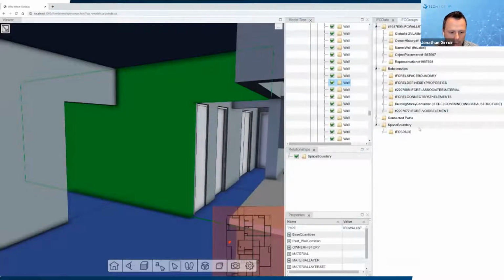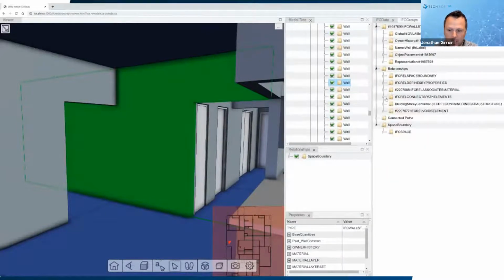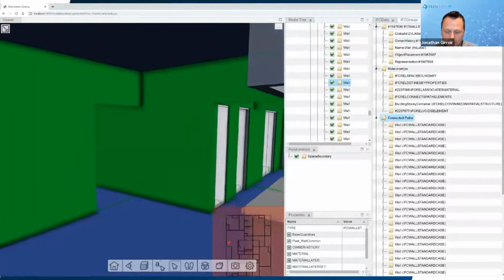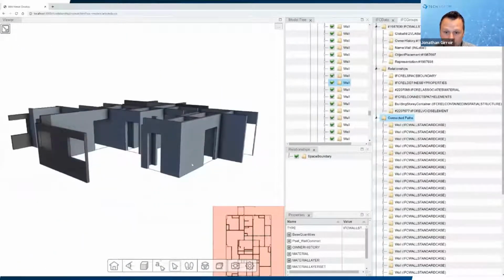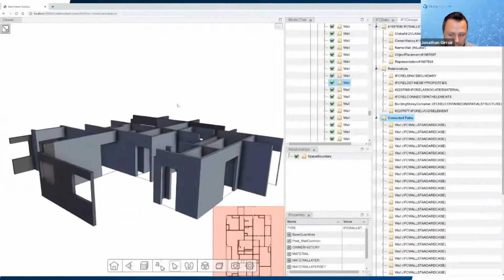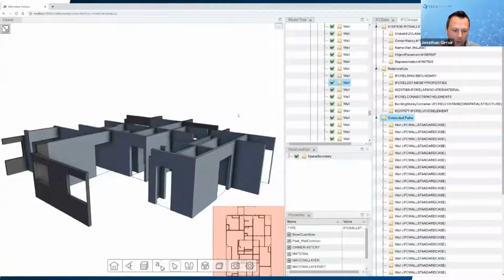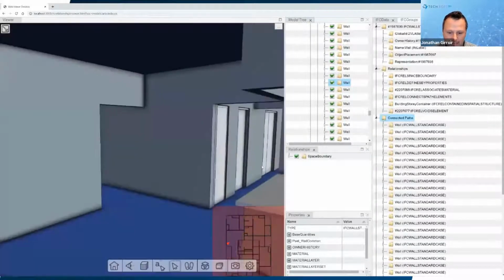So another IFC concept is this idea of a path. And so how is this wall connected to different walls within this particular floor? So we can look at all the connected paths associated with that. And again, isolate here, in this case, all the walls, all the paths associated with that for this one particular floor. This allows us to isolate not just walls, but we'll see in a minute, HVAC ductwork, and navigate categorically your data, your 3D data, given all of this connected metadata.